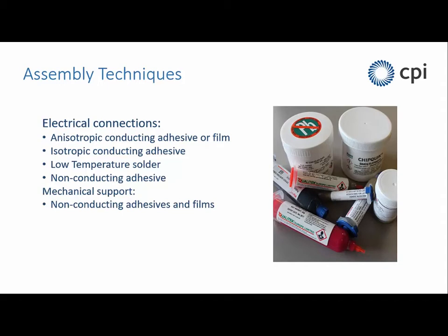However, it can be done, and it works extremely well. By choosing the right connection processes and the right adhesives and so on, we can make extremely reliable assemblies of combinations of rigid and flexible components that have superb electrical performance. And we tend to do that by using conducting adhesives. So solder can be used. Solder is the way that we make PCBs, of course, with conventional components.